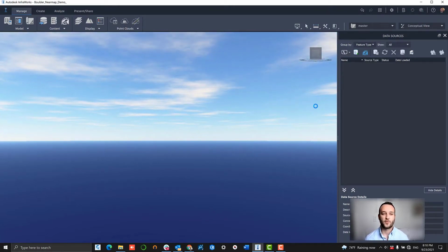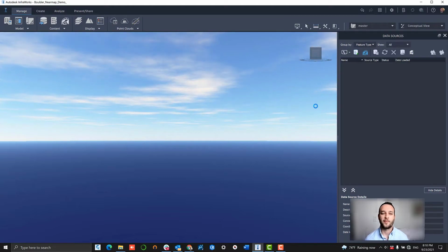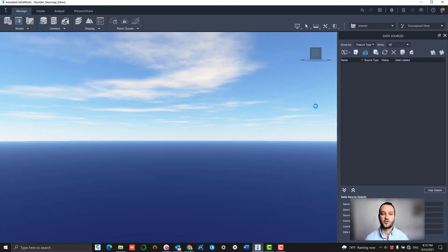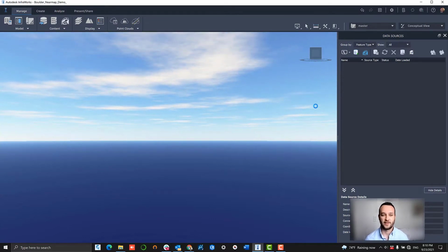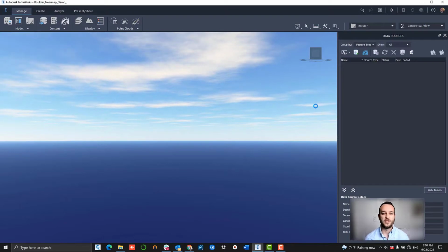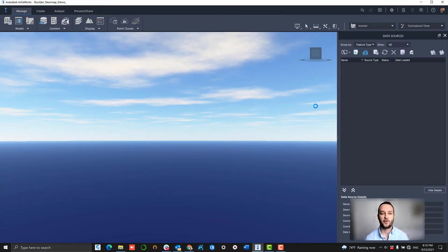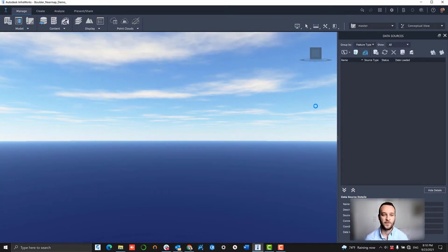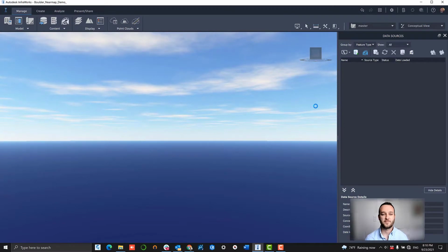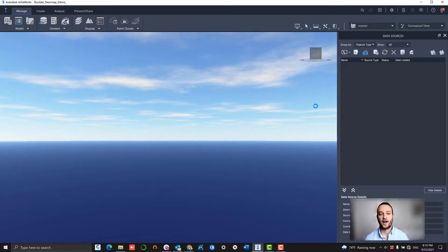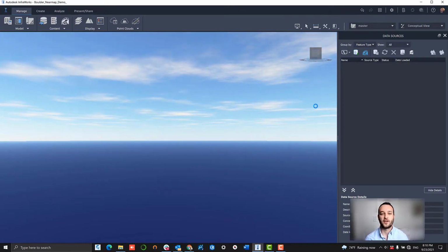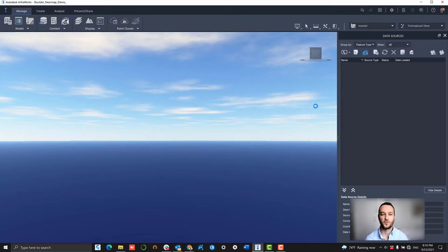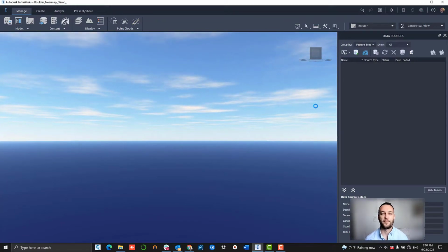Before we get into that, let's run through each content type and how Nearmap produces that data set individually. So the first piece of data is actually a derivative product. This is our terrain data set, our digital elevation model. And we generate this after each flight by using photogrammetry techniques to establish 3D terrain information off of our source photos. This is going to help us establish that 3D base map. And then after that, we're going to overlay our high resolution 2.2 inch ground sampling distance data on top of it. That's going to give you your actual visual photo overlay on top of the terrain.